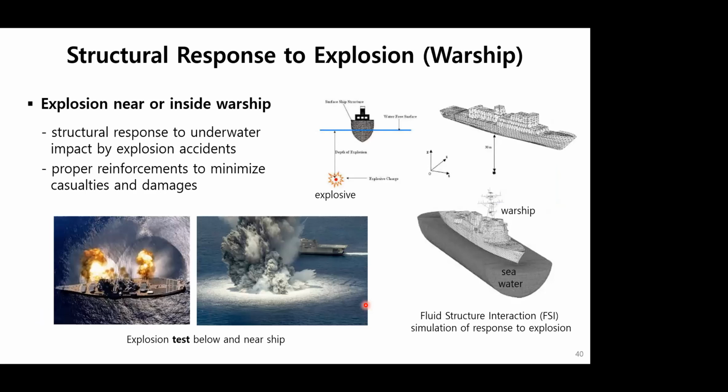Another special loading is explosion. This case is kind of limited to warship. You may imagine many scenarios of explosion near or inside a ship. What warship structural designers should understand is how the ship structure responds to underwater explosion impact, because they need to carry out proper reinforcement to minimize casualties and system damages.